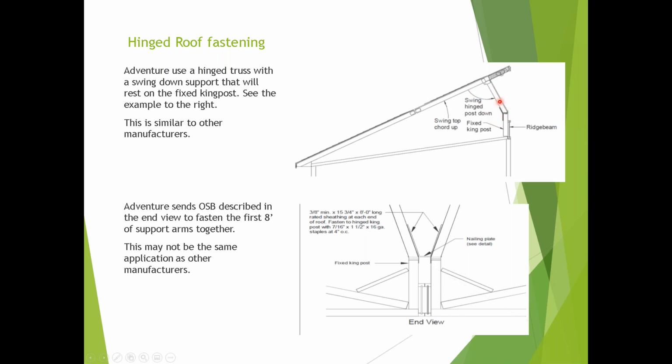And then this right here is where I'm talking about different engineers come up with different connection requirements. It's not only the engineer, but sometimes it's the truss manufacturer that dictates how this all has to go together for the different wind loads and roof loads. You don't have to know who the truss manufacturer is, or who the engineer was. The information should be in the installation manual.